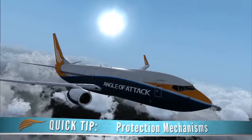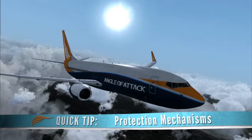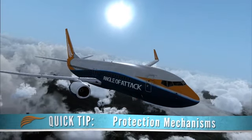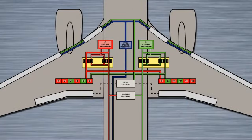The mechanisms for flap load relief, asymmetry and skew detection, and uncommanded motion detection are not available during alternate flaps extension operation. This system will be explained now. Alternate flaps and slat extension. We mentioned previously that the hydraulic system B powers flaps and slats in the 737 NGX. When there's a System B failure, alternate extension allows for flaps and slats to be operated with an electric motor. The standby hydraulic system supplies standby hydraulic power to operate flaps and slats during alternate extension.